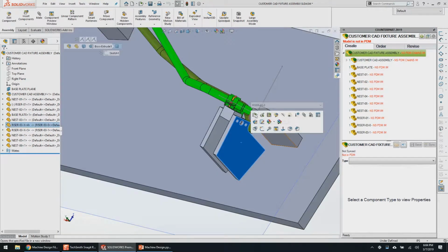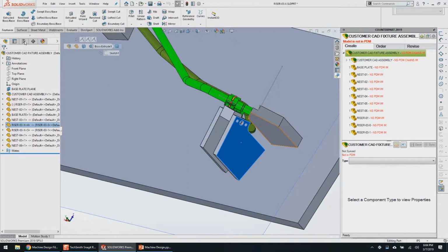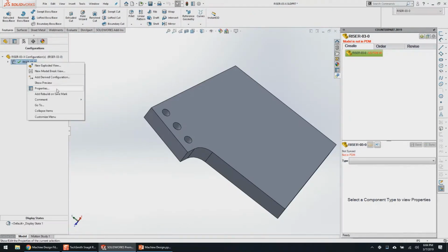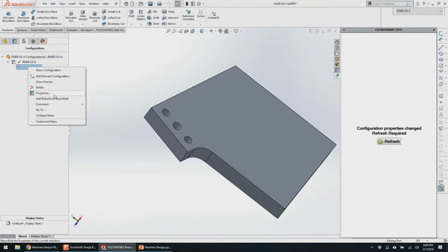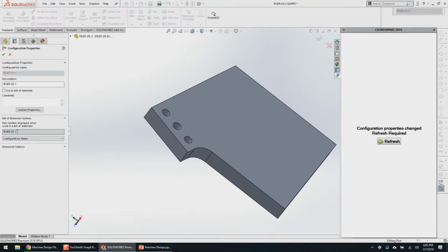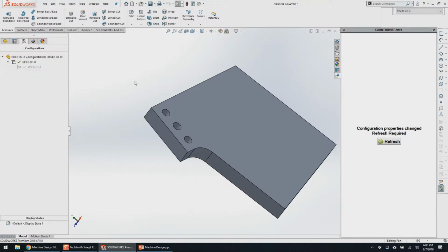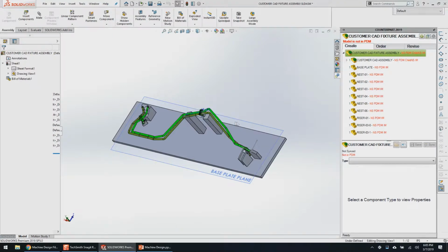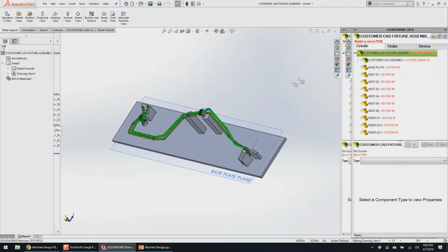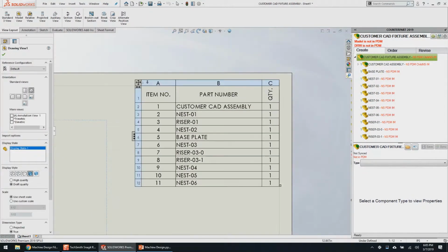The key there for SolidWorks or for Counterpart just integrates with SolidWorks and does whatever SolidWorks says. So this isn't a Counterpart specific thing. The key is that in this part file, in the configuration manager, bill of material properties, we choose configuration name. So this configuration reports to SolidWorks, which is what Counterpart uses, that its name is 030, and this sub-configuration name is 031. So that's a SolidWorks universal rule. Counterpart just uses it. It's not a Counterpart demo today, folks.